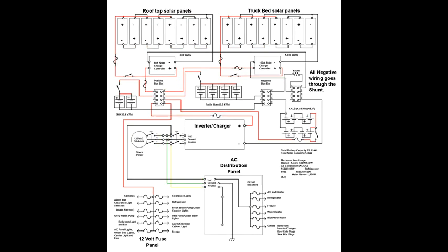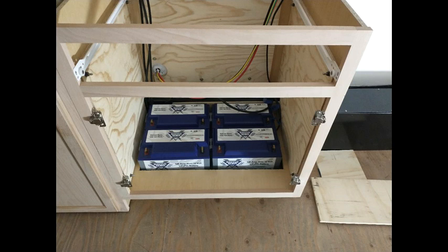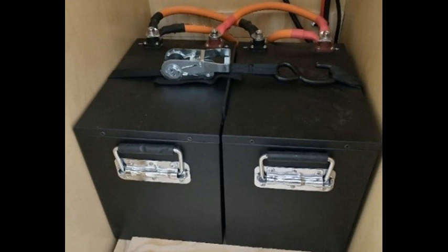This is a sample of my cargo trailer conversion schematic, which features 16.5 kilowatt hours of batteries. It was built with components that I already had on hand in order to save money. There are three separate lithium iron phosphate battery packs plus the EcoFlow Wave 2 battery. One battery pack consists of four Battle-Born 12-volt 100 amp hour batteries all in parallel. The second battery pack consists of two SOK 12-volt 206 amp hour batteries in parallel.